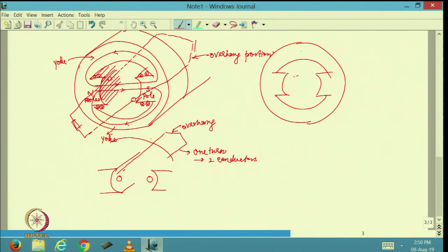I am going to have the rotor here. The rotor is going to have slots in the external periphery like this. You can imagine this is the rotor stamping. Several stampings together are stuck together to make the rotor. If there is one conductor here, exactly opposite I will have one more conductor here. So, let me consider only two conductors here. Now, the rotor will have a shaft in the middle, and this is going to be rotated with the help of a prime mover.